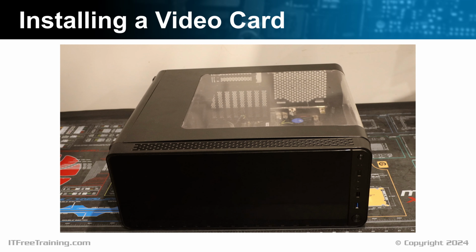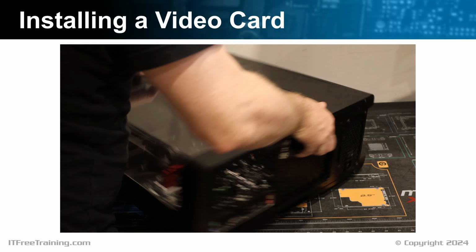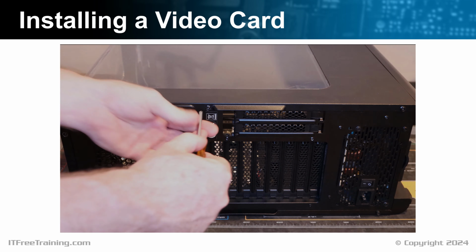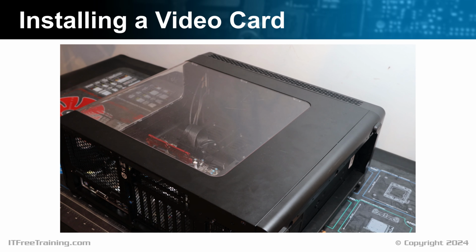To install a video card, I first need to remove the side panel of the computer case. For this computer case, there are 4 screws that need to be removed. Once the screws are removed, the side panel can be removed. Some panels will require you to slide the panel before it can be removed. For this computer case, I need to push it down and then lift it upwards to remove it.